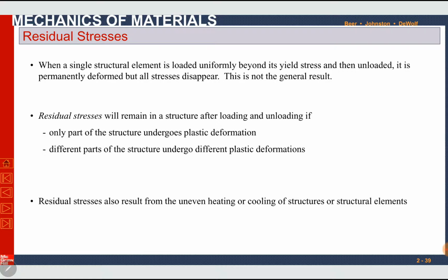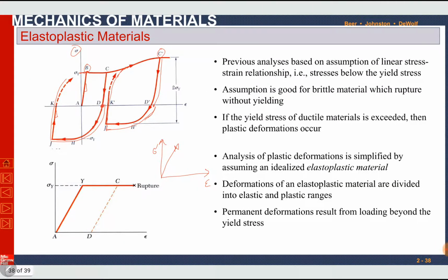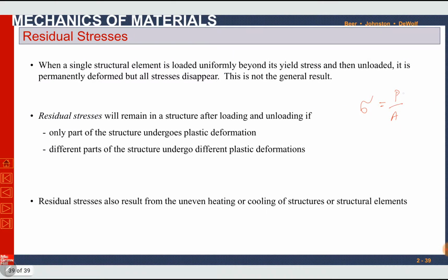This is not the general result. We think stress is equal to force by area, and we generally assume that when we unload a material from the permanently deformed point, if the load is zero, the stress should be zero, but it is not the general case. This will be the case only if the material is unloaded before the elastic limit or before the yield stress. But if a material is allowed to deform permanently and then the load is removed, the net stress will not be zero. Residual stress will exist.